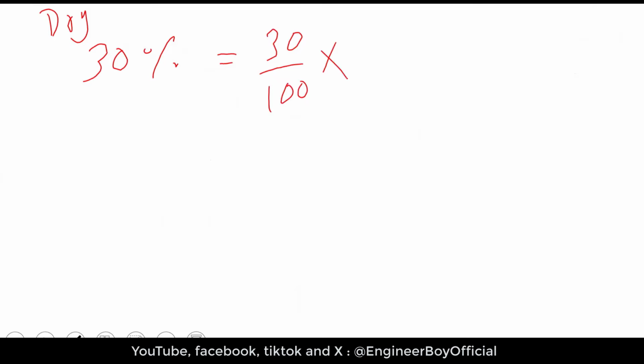Remember, the quantity of mortar should be 30%, and this is dry mortar. 30% of the brickwork is 30 by 100, and we multiply this with the brickwork, which, if you remember, was 373. So this should now be approximately 111 CFT of mortar.